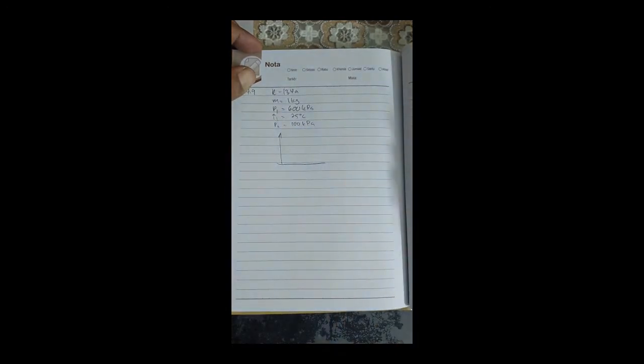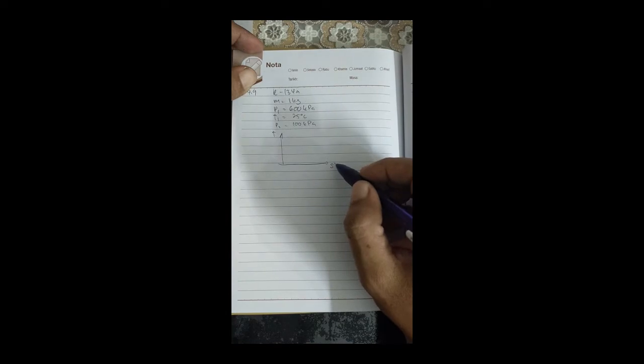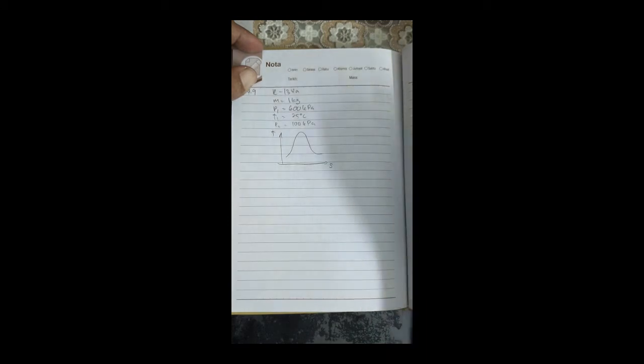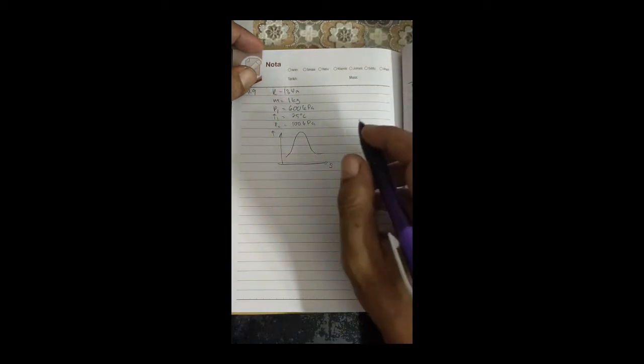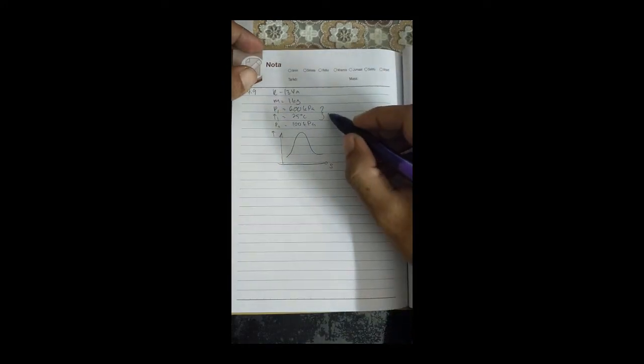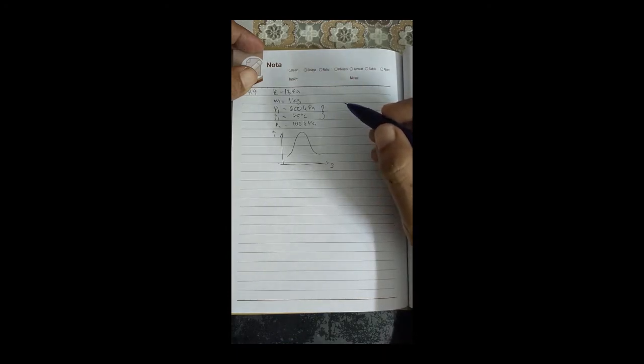Here we are dealing with entropy, so it is better for you to draw a T-S diagram, because if you are dealing with entropy you get a straight line. So this is your bell shape. First of all, check where this location is in the tables, either superheated or mixture.